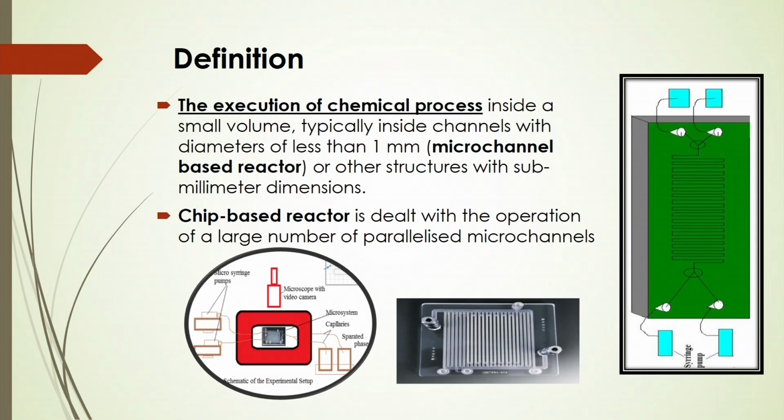The execution of that chemical process inside that small volume, typically inside channels with a diameter less than 1 millimeter, or other microstructures with sub millimeter dimensions, is very complex, and you have to precisely devise that micro reactor by considering the micro channel array having micro mixing and even other mechanisms, so that there will be an intensification of the process there.